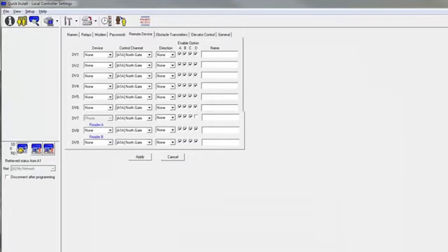DV7 is the keypad on the front of a telephone entry unit and cannot be changed. We can change what relay we want it to fire, but we cannot change what it is. DV8 and 9 are for 26, 30, or 31-bit Wiegand devices, such as card readers. In this case, we have a keypad addressed as DV1 on the AMKP.